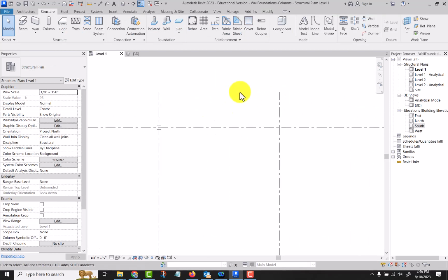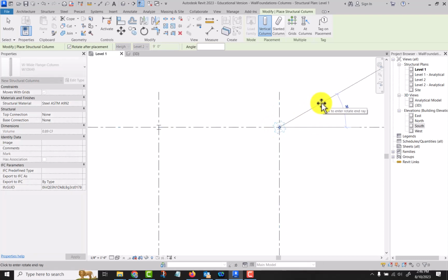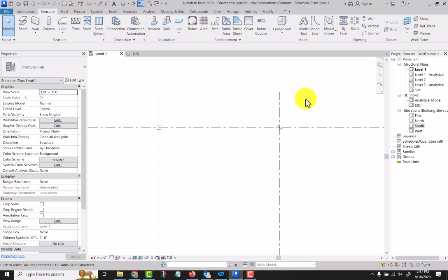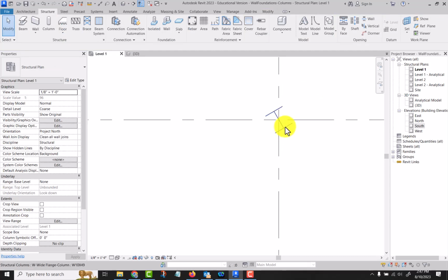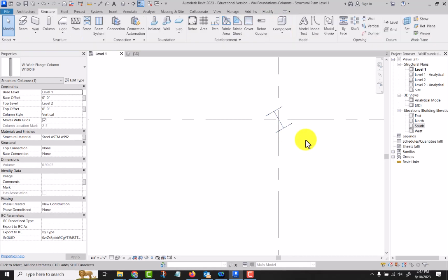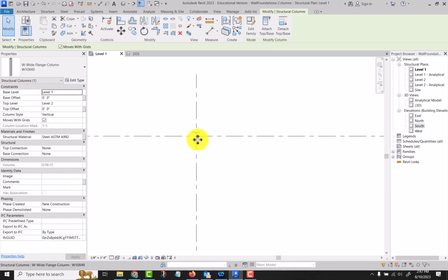Okay, so now let's look at another one, and let's do it again. And if I go rotate after placement, and then when I go in here to place it, I get a line, and I can type the angle I want. Oh, I clicked and it placed it at 30 degrees. I was one step ahead of myself. Okay. And if I press the spacebar it rotates at 90 degrees based on what my first placement was. All right, so I want to delete both of those.